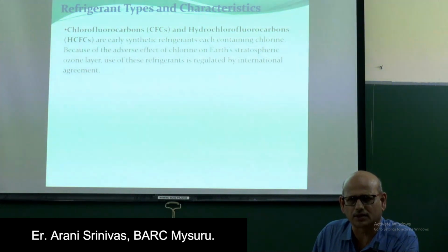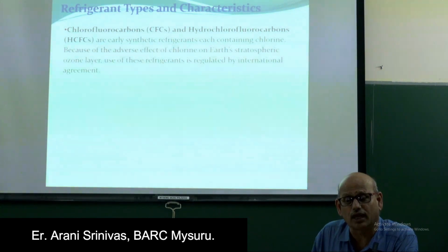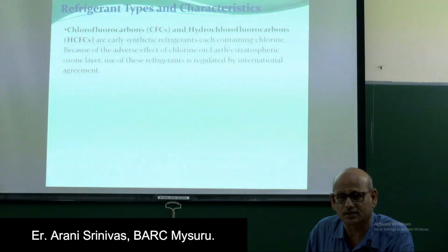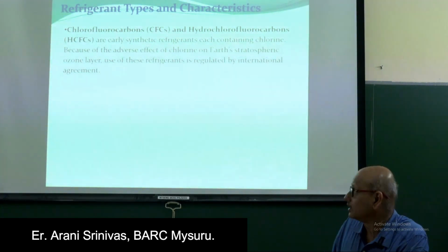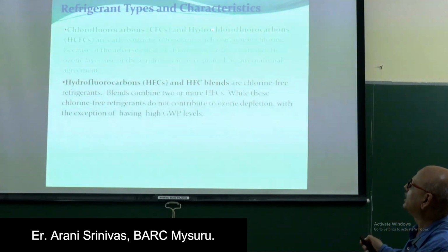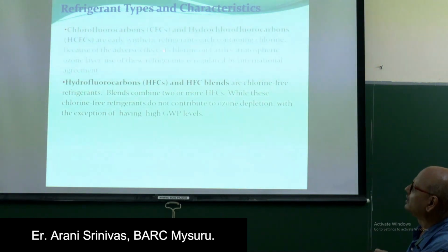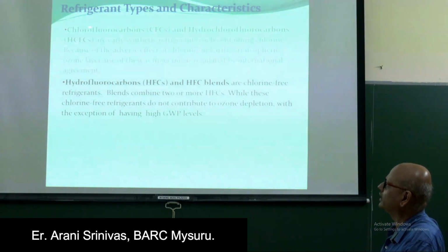In the vapor compression system, we wanted a refrigerant that gives higher latent heat. So CFC gases were invented, that is chlorofluorocarbons. Chlorofluorocarbons and hydrochlorocarbons, HCFCs, are early synthetic refrigerants, each containing chlorine. Because of the adverse effect of chlorine on Earth's atmosphere, the stratosphere, the ozone layer, use of these refrigerants is regulated by international agreement.